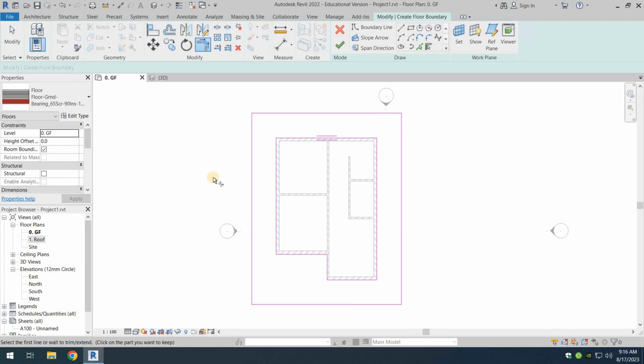Okay, now that we have joined it, you can see that it is quite a rectangular kind of area. But if you don't want a rectangular kind of area, what you can do is you can select the fillet arc option and then choose both of those and give a radius of your liking. So at first we're just going with a random number. Again, on this side we're giving it another radius, let's say like that.